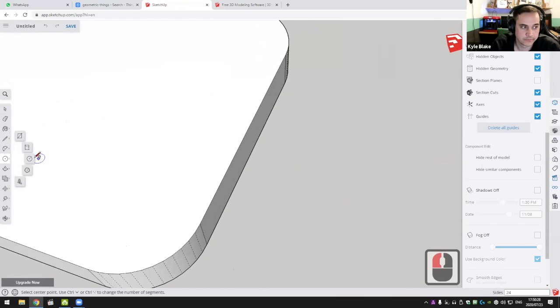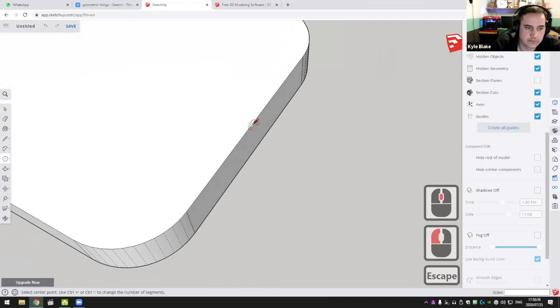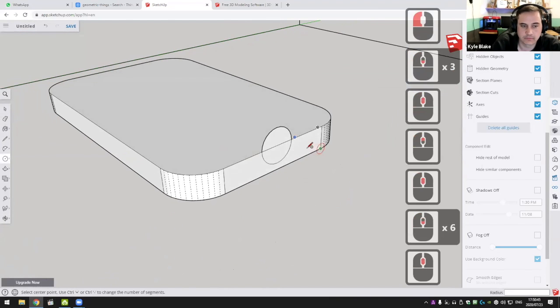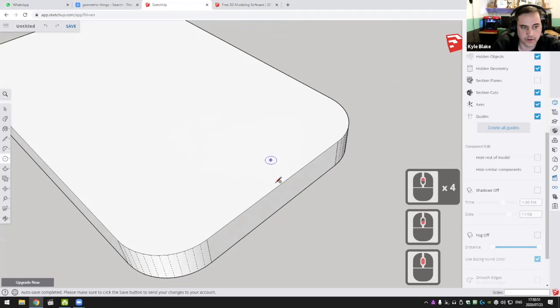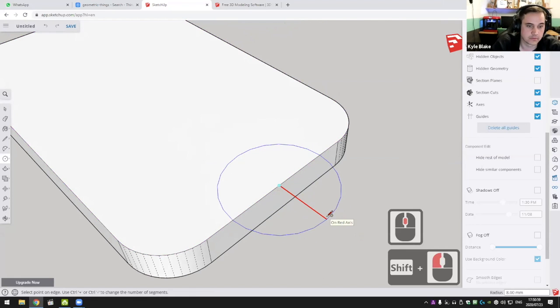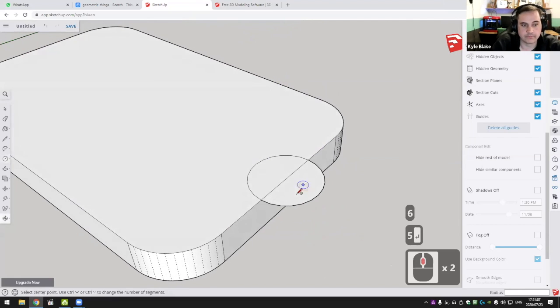It's a circle tool. You can snap to the center. It will go blue automatically. I think sometimes someone might have a problem where it snaps to the red plane like that. Then it's actually drawing on a different plane. So you would want it to draw on a blue plane. You can lock them. So if you want to draw on this surface specifically and you press shift, it'll go pink like that. That means it will snap to that plane only. Then you can press shift again. But yeah, okay, 5, 6 mils. Pull down the face.